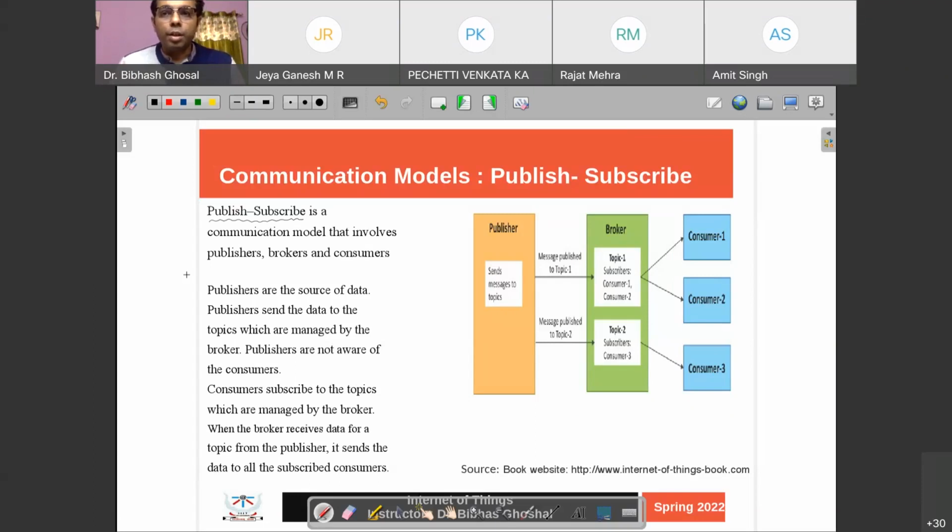For connecting computers, it's easy because all are mains powered. But if you have a battery-operated device and you always connect it to a particular device, there is a chance that the battery will drain out. So you cannot keep a small IoT device always connected to some heavy computer. Or you would have to have some kind of main supply always plugged in, which is not possible in many cases. So you have to think of alternate ways of communication.